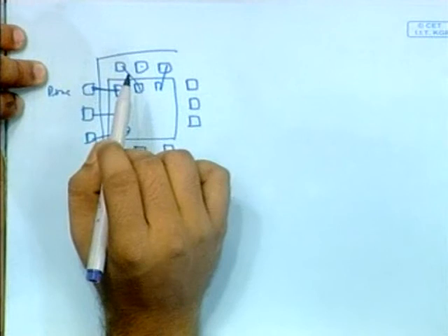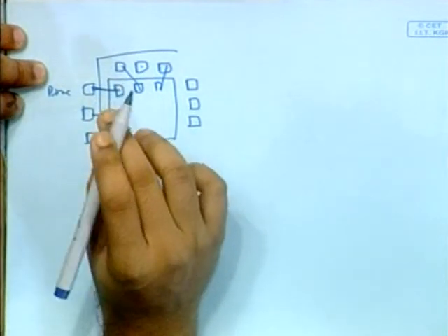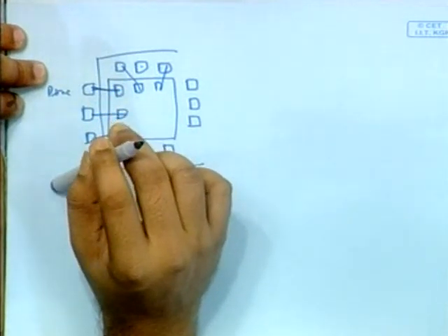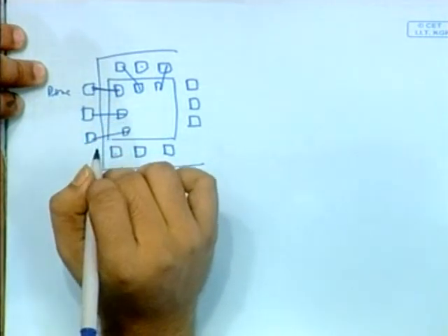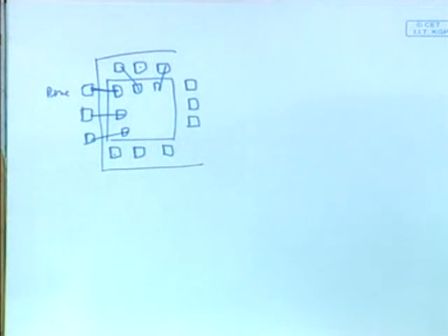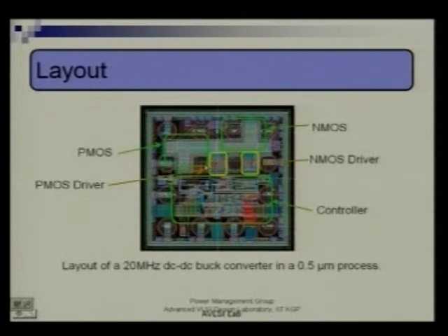But here, this has been designed on what is called a micro SMD package. What is this micro SMD all about? You will find these small balls. These spherical things ensure good ohmic contact. They do not have any bond wires because they are not pins; they are directly bonded to your die. So this is directly below the die.